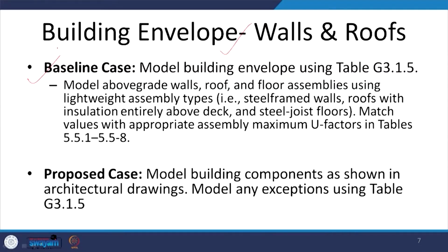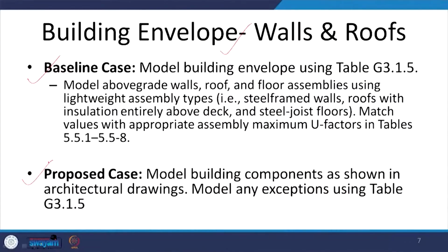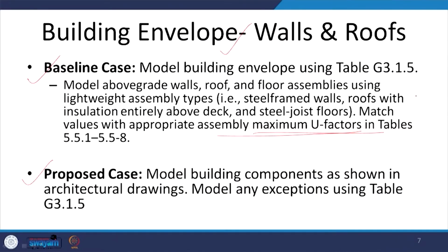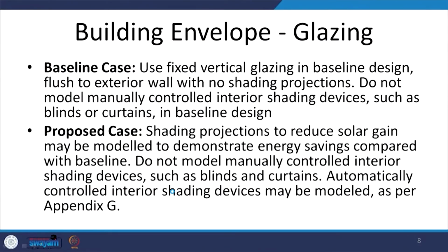When we are talking about the baseline method, the U factors, the U values, and SHGC of the building envelopes will be taken as given in the prescriptive requirement of the code. However, for the proposed case, we will use the building components and model them as per the architectural drawings and specifications. So, the maximum U values permitted will be the ones used in the base case. The proposed case may have higher or lower U values, as used per the specification.